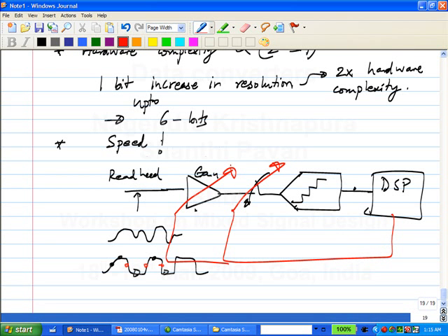So, in other words, this A to D converter has to sample at those speeds. Today it's common to see 1.5 gigabits per second A to D converters, which means that you have 600 picoseconds to sample, figure out which of these bins the input lies in and put out a digital word, and then 600 picoseconds later you have to be ready for the next input. So, an extra clock cycle of delay in the A to D converter can make the whole system not work at all because of the delay introduced by the data converter. Typically in disk drive systems you have 6-bit converters at several gigabits per second.